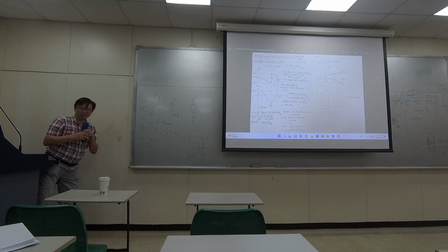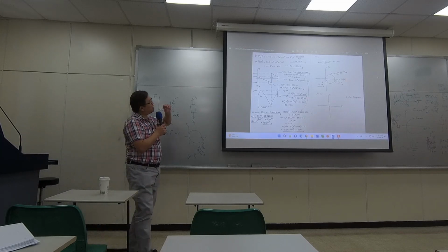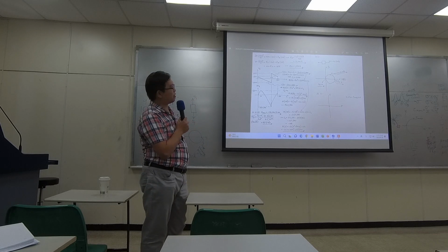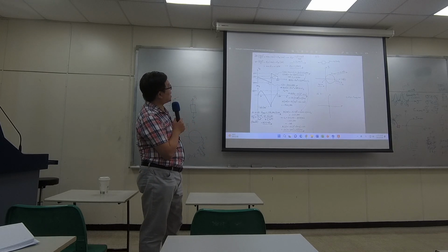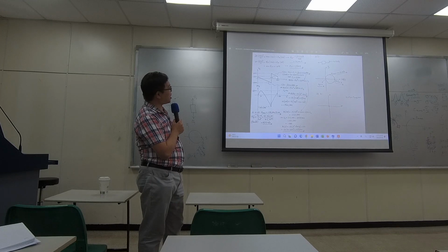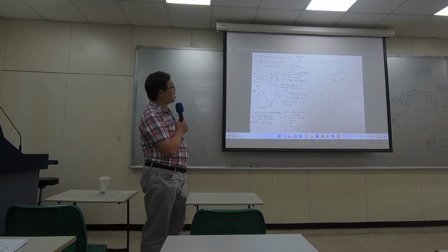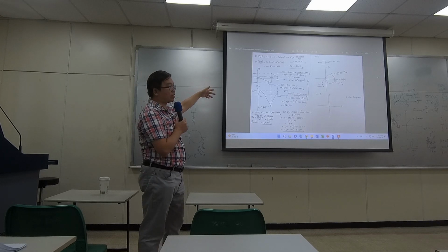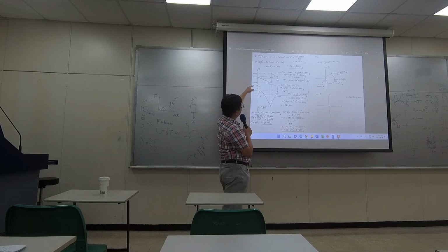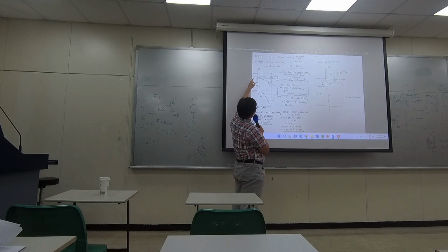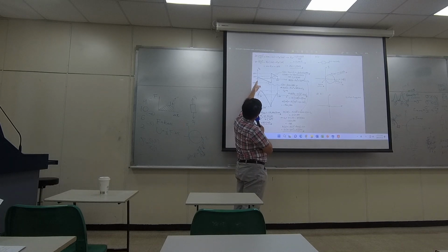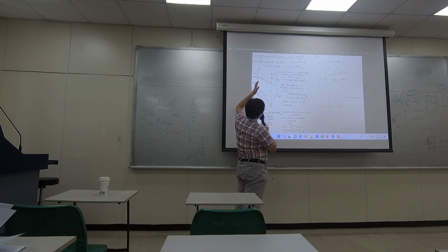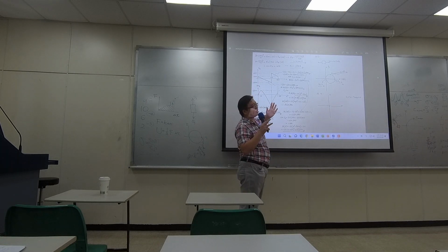So first you need to do force balance. Once you have the force balance, what I did was I used the trick to draw a shear diagram first. At the left edge, there is a reaction force pushing up, and there is a uniform distributed load everywhere.